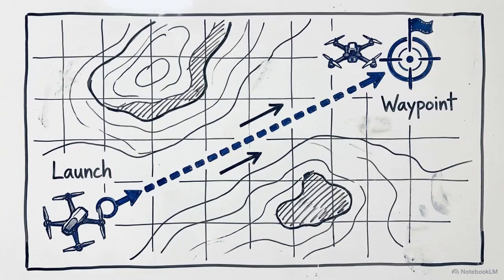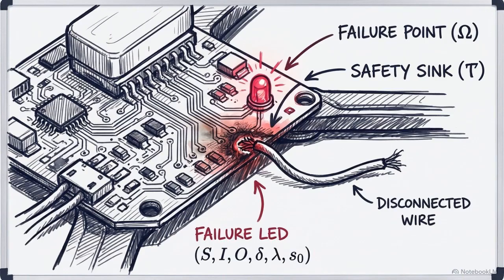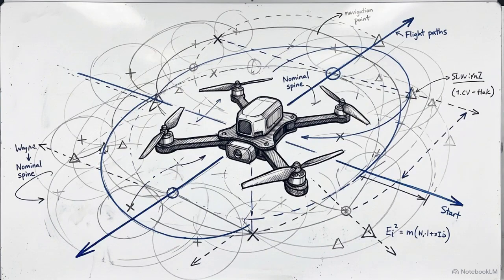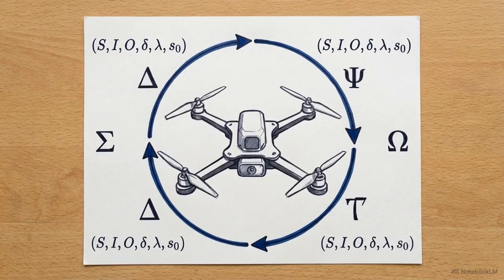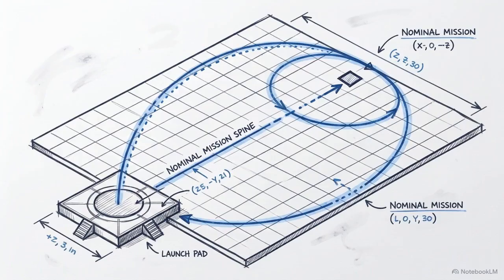To prove the system's reliability, the team must first map the ideal flight path and then test the architecture against specific hardware and environmental failures. This standardized baseline allows the team to verify safety protocols before adding complex multi-waypoint operations. The model starts with scenario S0. This represents the nominal mission flow: a startup, a flight to a single waypoint, a brief hover, and a return home. We can trace this flow on the FSM's node and edge graph.